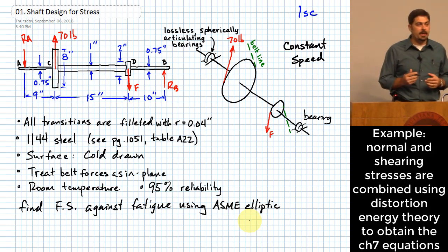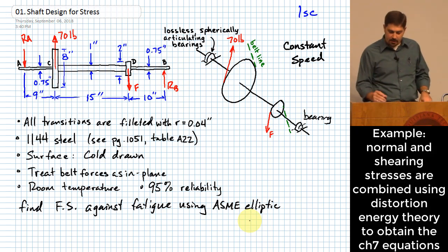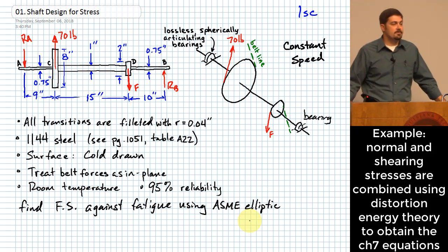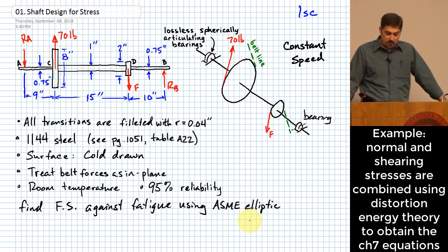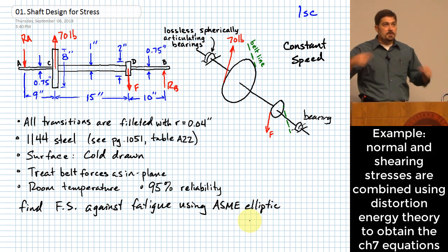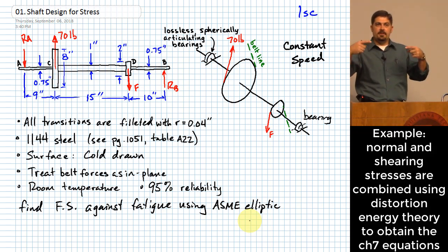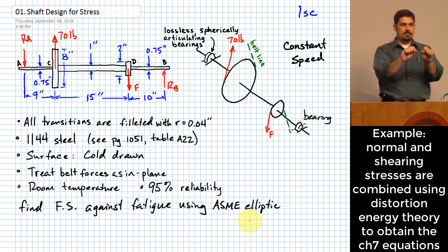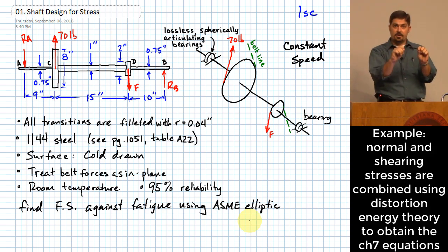So real quick, conceptually, what kinds of loads are applied to this shaft, would you say? Okay, it definitely has a torsion that is going to transmit between those two pulleys, right? As well as what? Okay, if it's rotating, which we're assuming it is, then what happens? Okay, it's being flexed and rotated at the same time. So it will have flexure, but that flexure is going to lead to a bit of a fatigue problem,